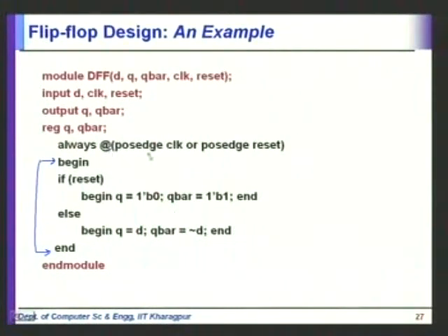So always @ posedge clock or posedge reset. What is posedge clock? It says that whenever the clock rises, positive edge of the clock, or whenever reset rises, in any of these two circumstances we are going to examine this.